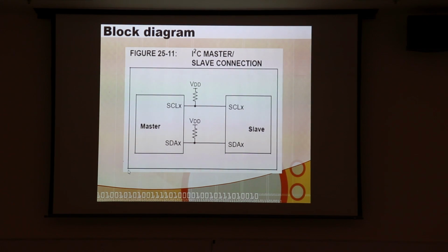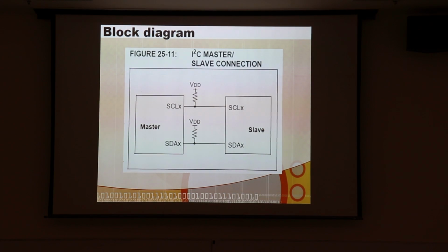The accelerometer and gyro in the same package typically have a little controller built in, and then they have a second I2C line that can go out and talk to a magnetometer, and then it has a little built-in processor that can take the magnetometer data and process it a little bit and give you a better solution on your accelerometer and your gyro with the magnetometer data.